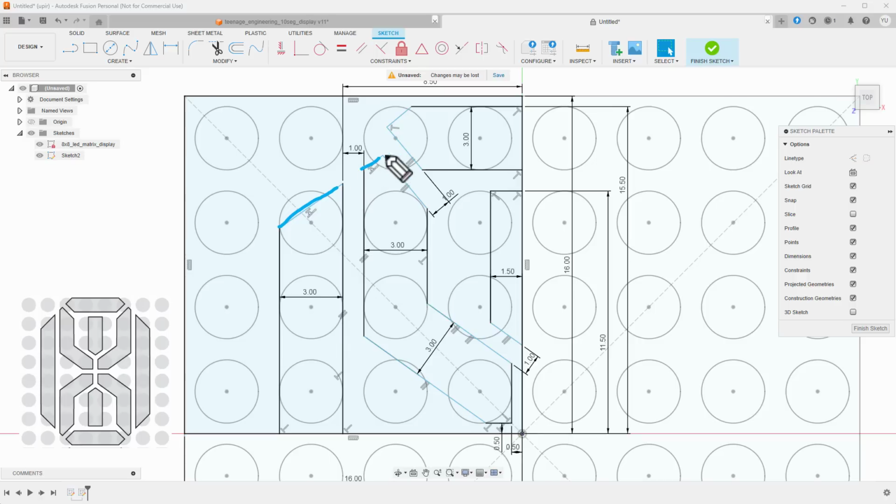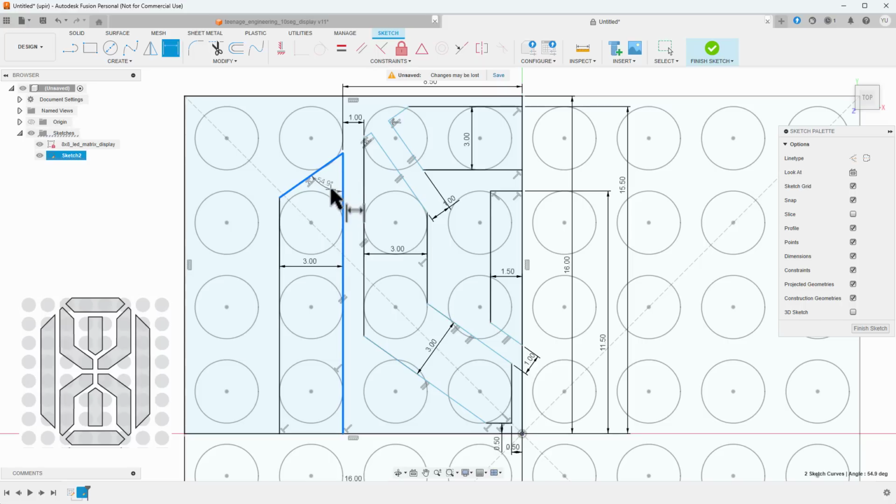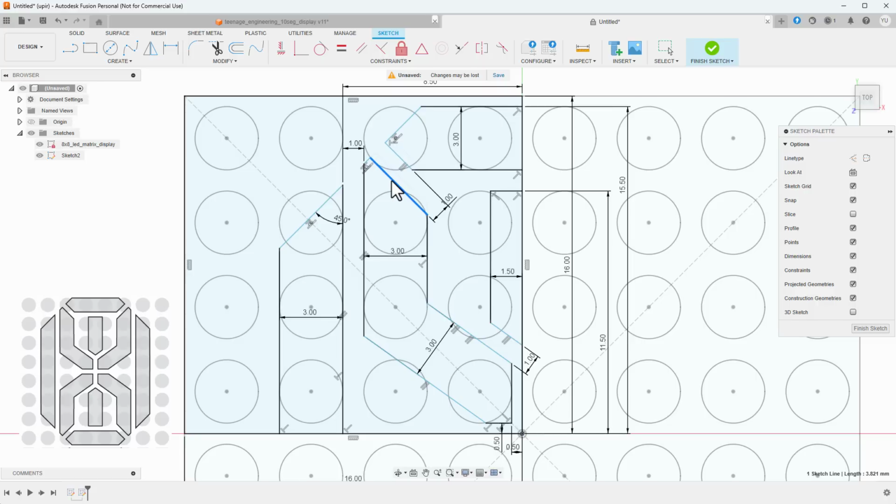And let's align all those three lines by applying the very same constraint, which is this one, the collinear constraint between that line and also that line. And then we can either move those blue lines or perhaps change this angle by setting again the sketch dimensions and maybe set this to be 45 degrees only to just rotate it slightly and move this down and maybe this to the left side.